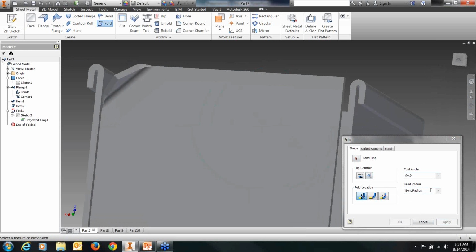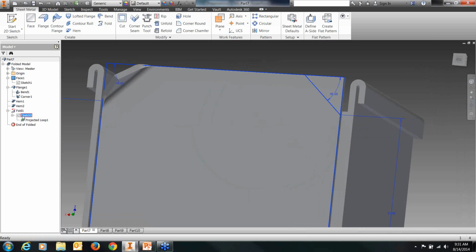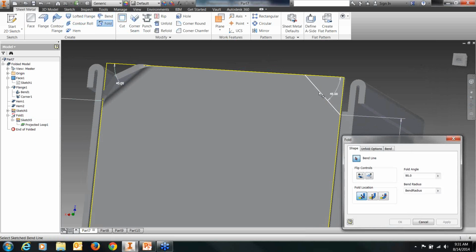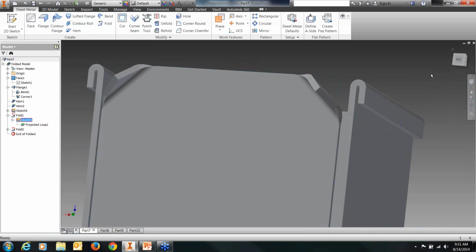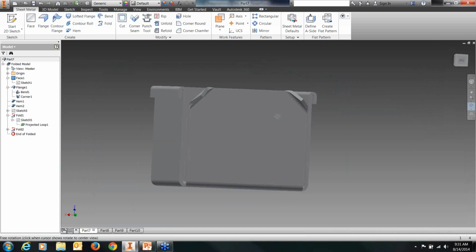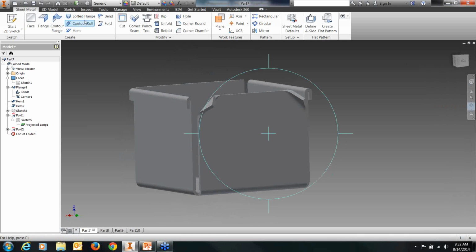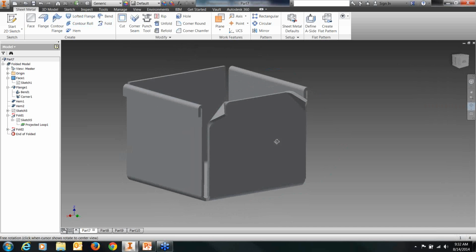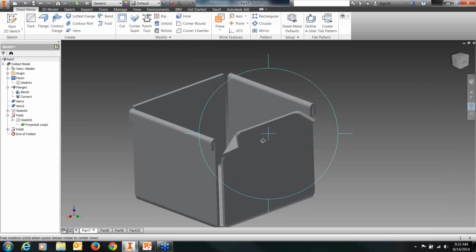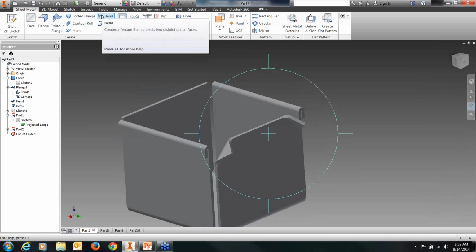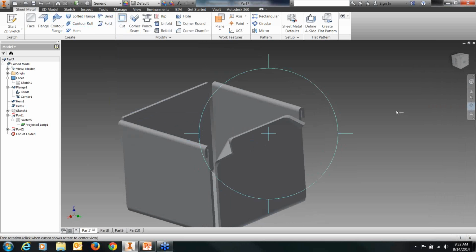Let's go ahead and cancel this. Let's share sketch so we can add another fold here. And then let's cancel that and let's change the visibility of that. So now I have a flange. I applied 2 hems to the side, and then I added a fold feature on this side. The bend feature is what's created if, what you need is 2 separate faces.